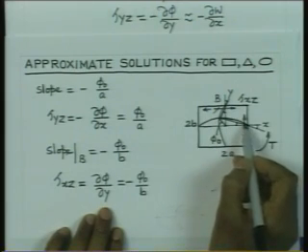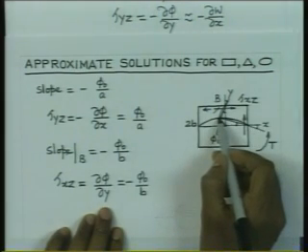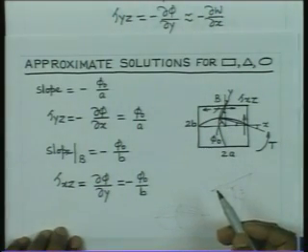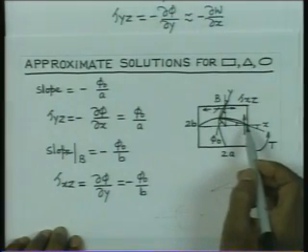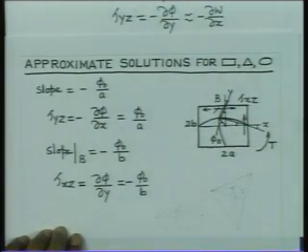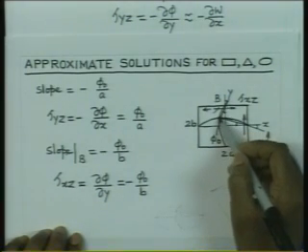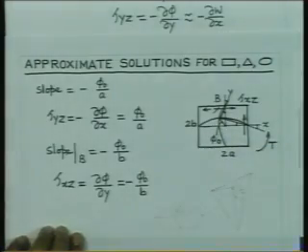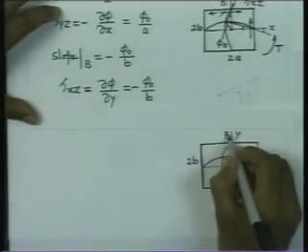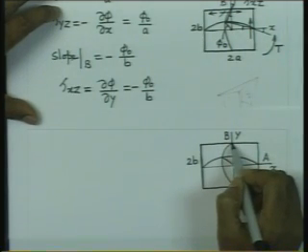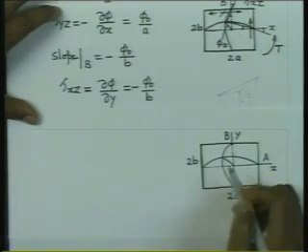In this case, you see that slope is maximum there, and it is gradually becoming 0 at this center. So, therefore, the stress is going to vary gradually, and in fact, it is a quadratic curve, it is going to vary linearly up to this center point to 0. Similarly, here the stress is maximum, and it is going to vary linearly to 0 at the center. So, we found that the stress is going to be maximum at this point B. Let us say that this point is A. Herein higher stress is going to act at the point which is closer to the center.